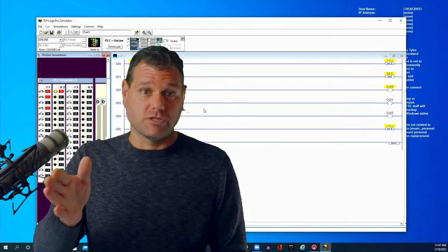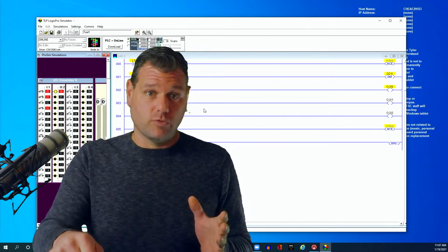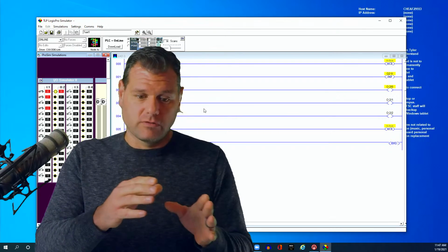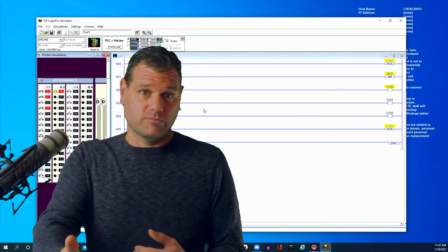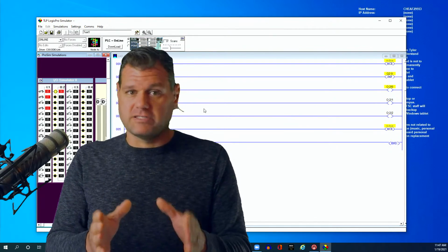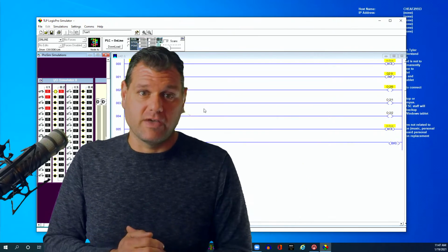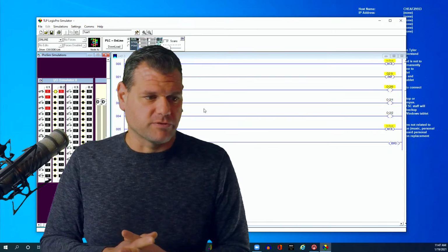So right here, when the MCR goes off, that jump is dead as well. So you never jump into an MCR, and you try not to put one inside. This would work because it would never jump to or from anything, since it's in the fence. But yes, an MCR does not affect anything outside of that fence. Does that kind of explain what you're saying?